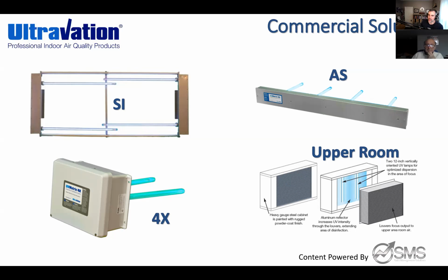I'm going to show this to you guys in a little bit. The upper room is actually something very popular over in Europe and other countries. And now it's getting popular here because there's no motors, there's no fans or anything in this. The upper room is called out in the ASHRAE handbook for big wide open spaces, like a huge cafeteria or a big common area inside of a commercial space, or for example, a big lobby, where they're trying to get additional air disinfection in those spaces besides traditional ducted. This is what's being added.